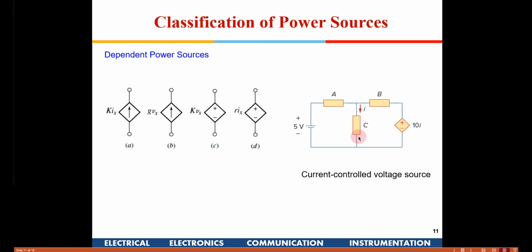You can implement it. Suppose I put, say, a one milliohm resistor in series out here, right? So if I take the voltage across that, it will be proportional to the current which is flowing in this circuit, and that 1 milliohm will not make much difference out here.